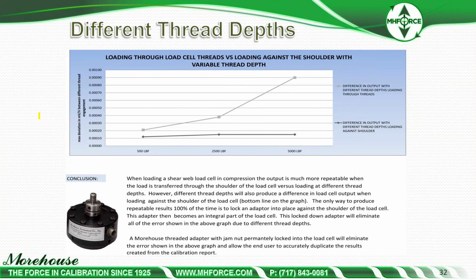The solution is to lock this in place. You put one of these adapters in place, lock it in, never take it out, use that with the load cell for eternity, and you will love the measurement results. Much more repeatable. It eliminates the thread depth problem. 100% of the time it's repeatable.